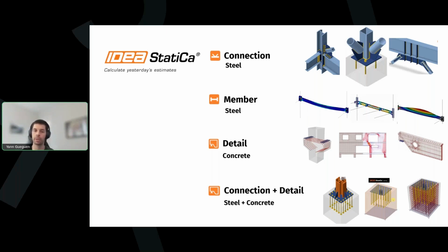This allows you to bring base plate or embed plate connections from the steel application into the concrete application to design your anchoring reinforcements, again with any kind of geometry. We're showing a rectangular pier here, but it could be a pedestal or a circular pier. Anything could work.